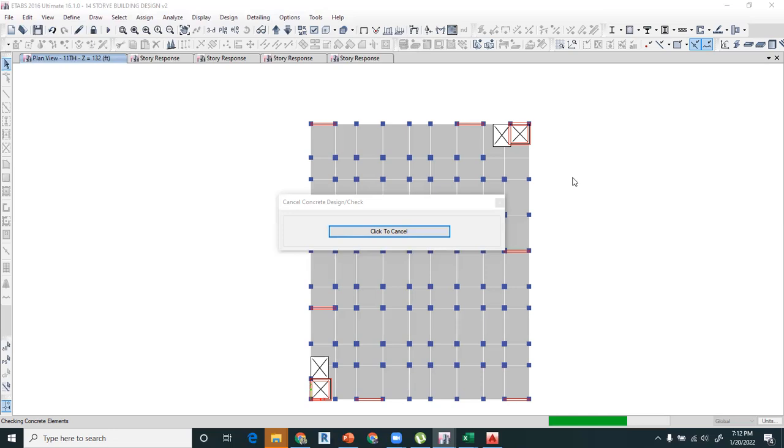But if you design your building, for example, in a region where there is no earthquake, if you design it for zone 1, the forces are very low compared to zone 3 and 4. So if you design it for zone 1, you will be on the safe side. If an unexpected earthquake occurs in your region, your structure will bear those forces. So it's a must to consider a small earthquake. If there is no earthquake in your region, then you are on the safe side. You do not have to consider any earthquake in your design. Go only for gravity loads.